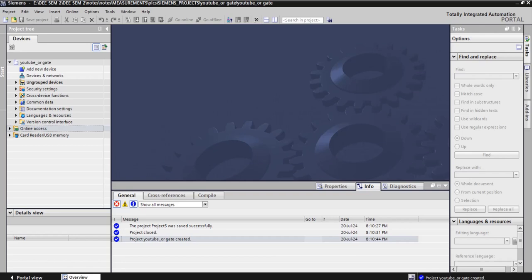And now, in this discussion, we are going to demonstrate how we can simulate in TIA Portal version 17 of Siemens. We are going to do this by running a simple logic operation of an OR gate. So we are going to do an OR logic operation whereby when you have one input high, you always have a high output.